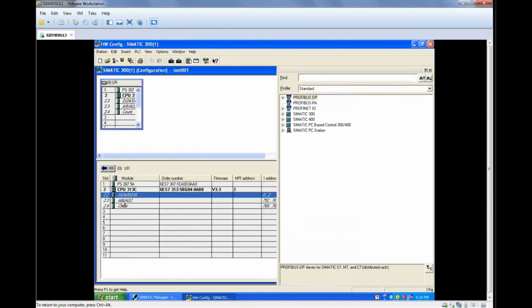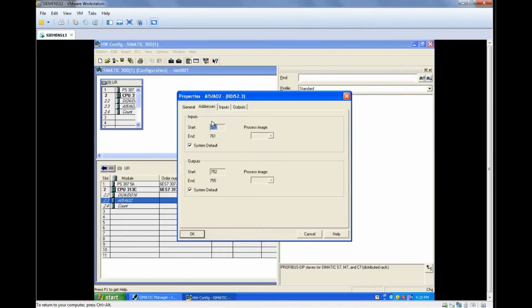I want to start with the continuation. Already we have used 3 channels for input. So here I am going to start with the 3. Here I'm going to start with the 2. Fine. So why I have given 3 is, for the digital input I have used the first 3 channels. So the next one is started over here. The first 2 channels were used by the DO. So for analog output it should be started with the 2. That's it. Click on save and close this page.